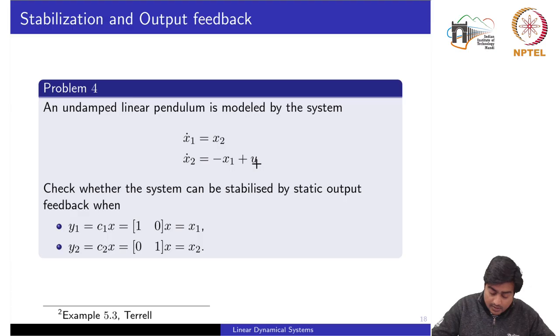If you recall the concepts of controllability we had discussed earlier, I can directly obtain the ABC matrices of these two equations. Now if you check the controllability of the pair A, B, it would be controllable. Now what we want to see, whatever the concept we had studied about controllability, is there some relationship between the controller state feedback or the output feedback controller design? Because do not forget that the concept of controllability we had discussed is only about the state. So basically we should refer to it as the state controllability.